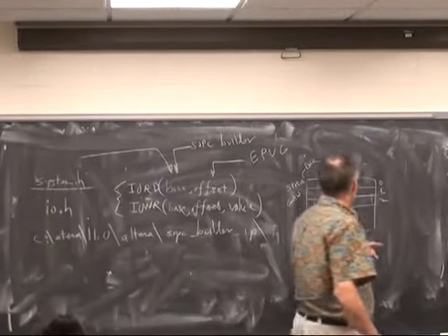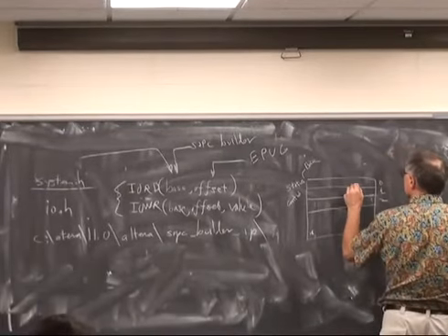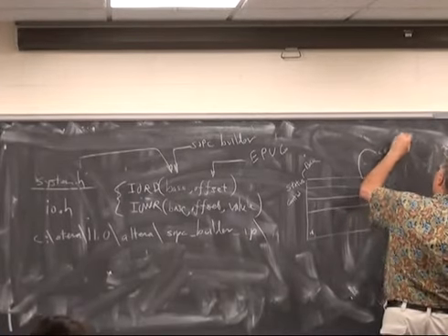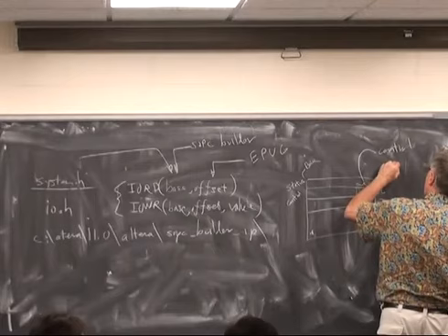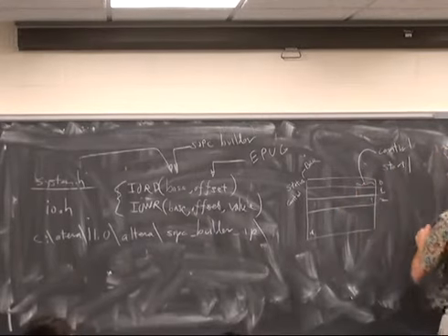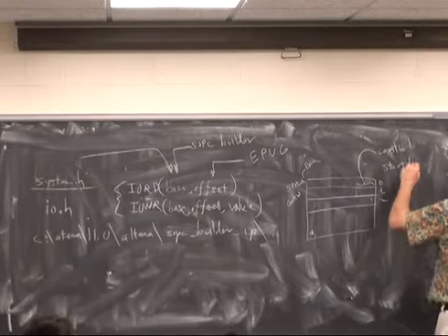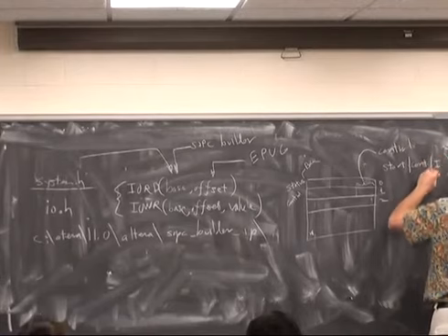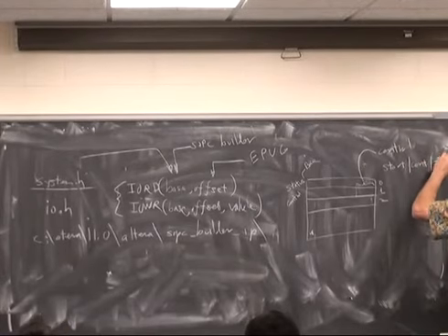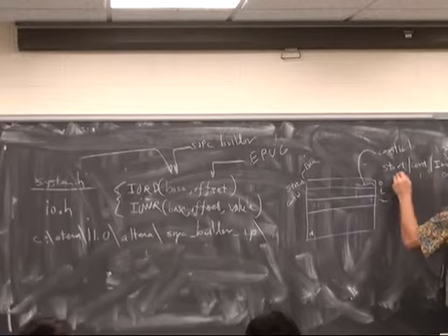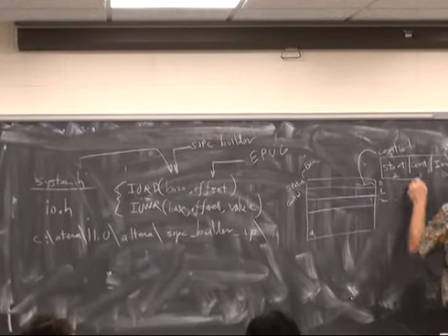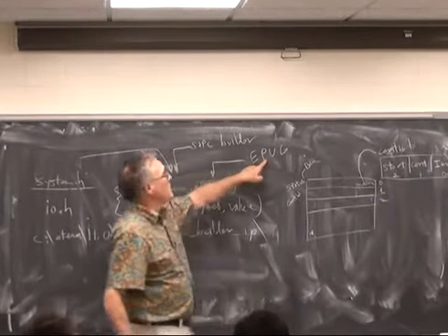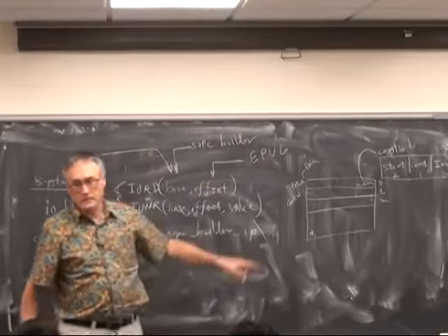For instance, for a timer, the first 3 bits, the control bits, are start, continuous, and interrupt enable. So this is bit 0, 1, and 2. And those definitions you would also get from the Embedded Peripheral Users Guide.